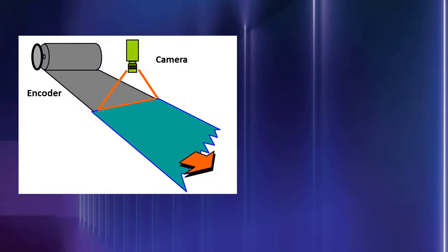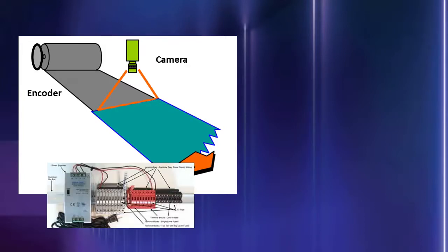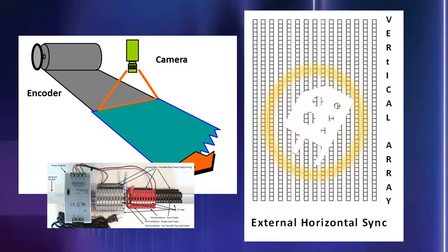Linescan cameras don't have the synchronization overhead of array cameras. Their high speed and resolution result from offload synchronization and processing downstream, so that their scan times are much faster, with rates of a millisecond or less that are common. To obtain a 2D image from a Linescan camera, the individual lines are combined, one after another.